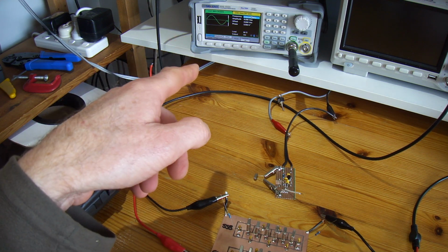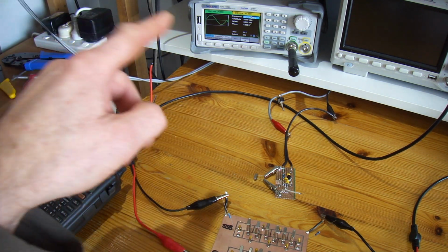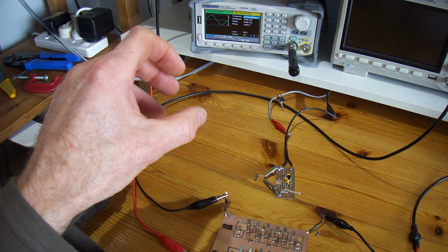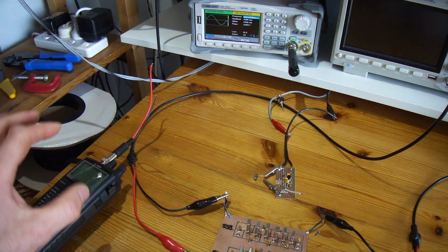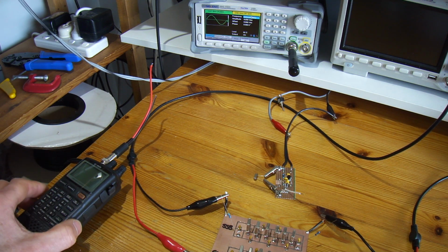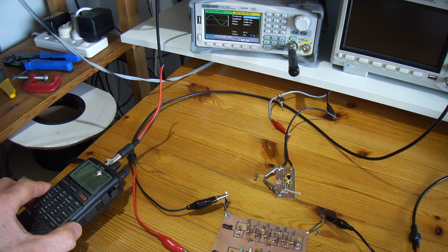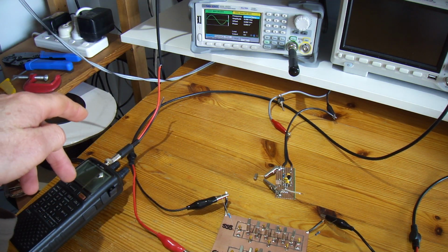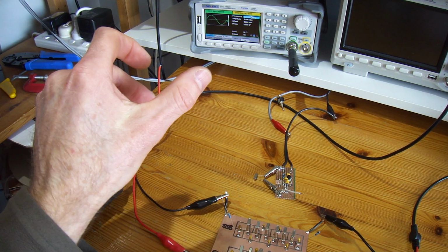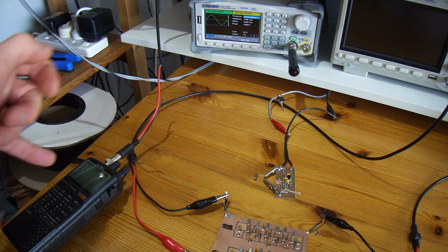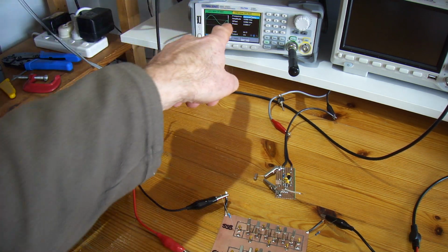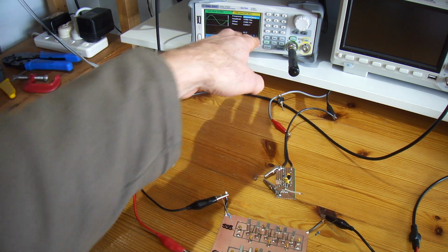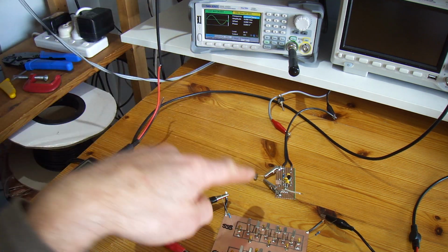on the same frequency. And if I get the SIG-gen to be on exactly the same frequency as the crystal oscillator, I get a single tone coming out of the radio. When I get slightly off frequency, I start to get a beat frequency. And the approach is to basically adjust the signal generator till I get a 0 beat, and then I can read directly off the SIG-gen, because this goes down to 1 Hertz, what the frequency is for that crystal.